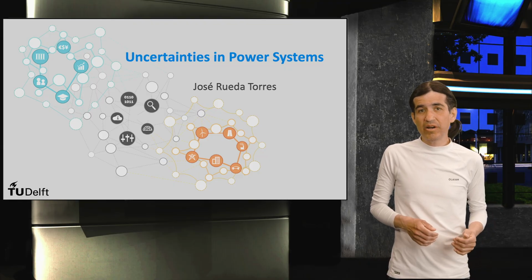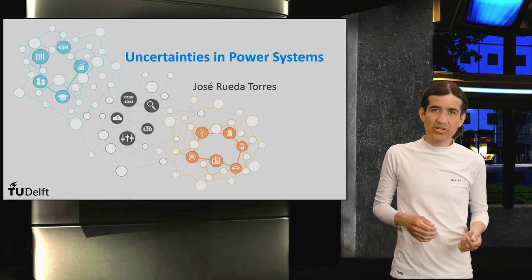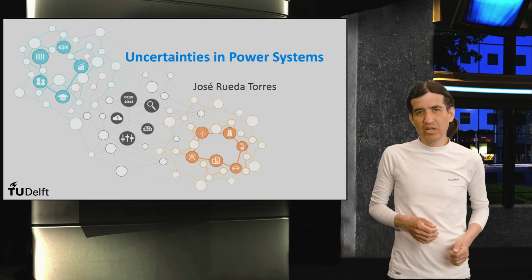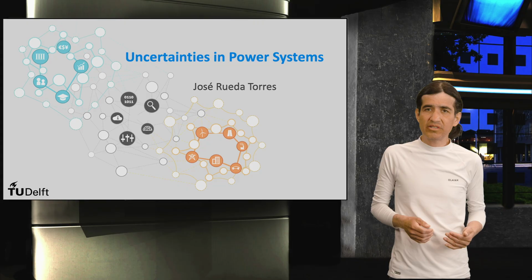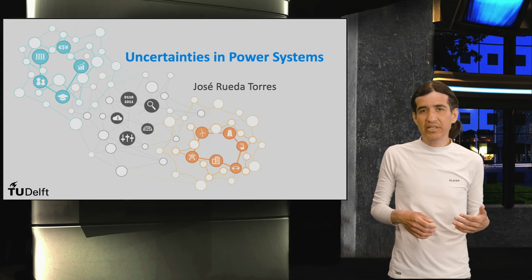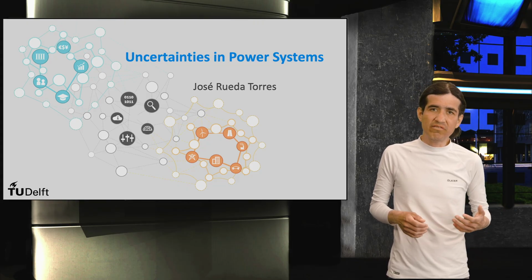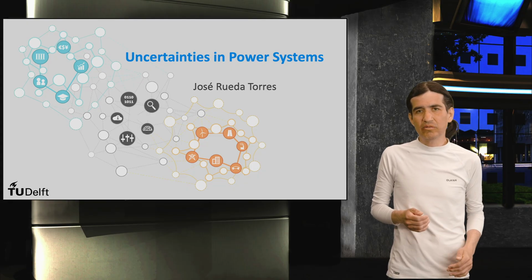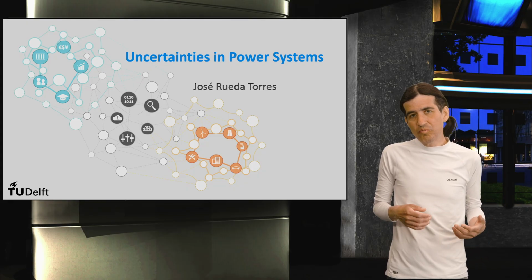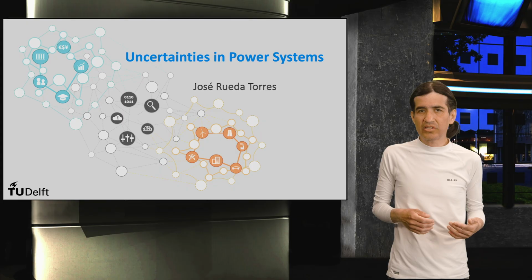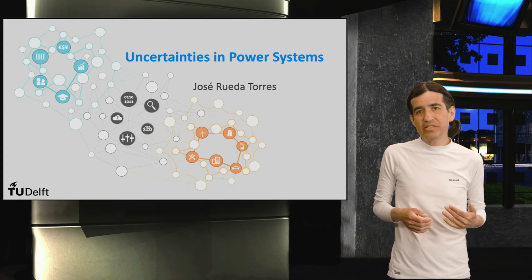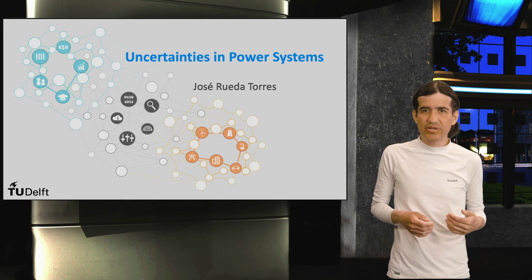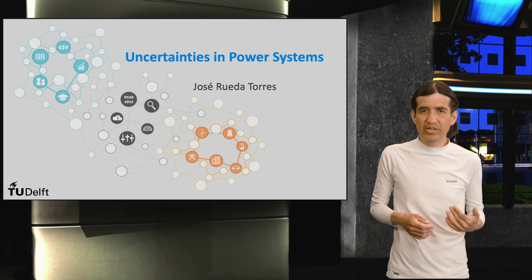This week, we learn about probabilistic power flow calculation. In short, probabilistic power flow evaluates power system behavior under uncertainty by modeling inputs like loads and generation as random variables, producing probabilistic outputs like distributions of voltages and power transfers. Instead of single deterministic values, like an operational snapshot of the system when operating at a peak demand.